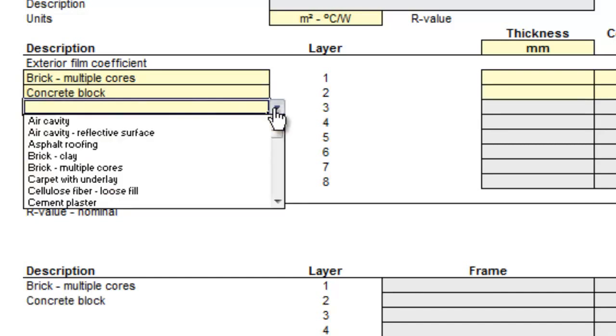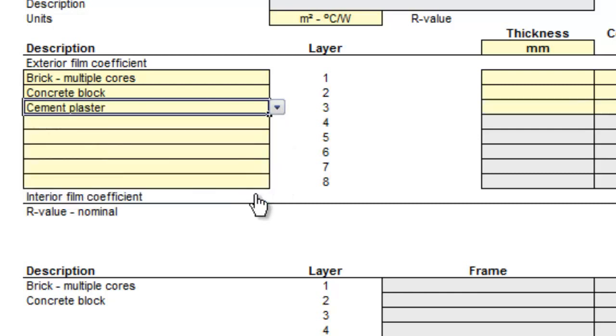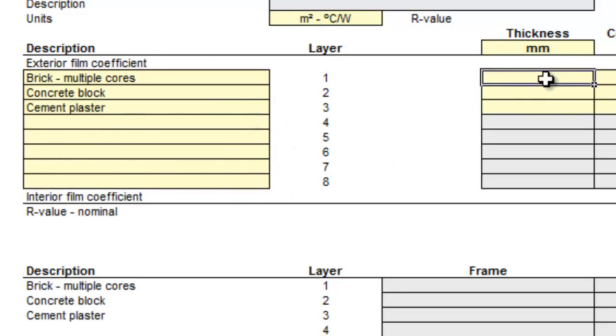In this example, factors that would reduce the nominal R value, such as framing and envelope penetrations, were not specified. Therefore, the nominal and effective R value are equal at 0.745.